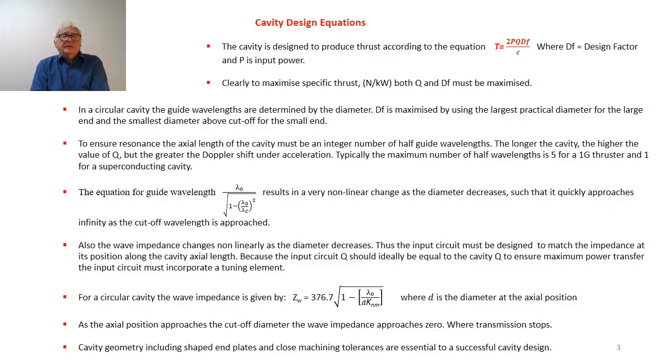And if you look at the equation for guide wavelength given in the slide, you can see that first of all, it will produce a very non-linear change as the diameter decreases. And indeed, when you reach cutoff, the guide wavelength goes to infinity because the wave stops. And you can see that lambda c is incorporated into the equation. The other thing that happens as the diameter decreases